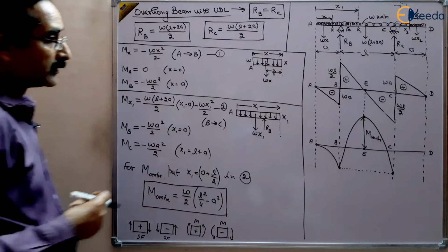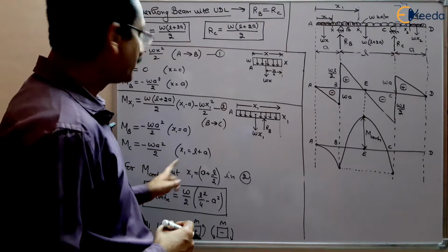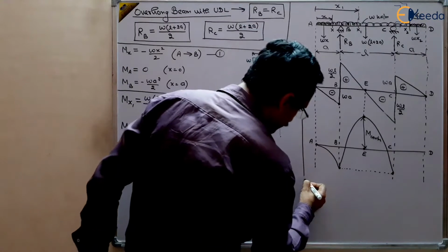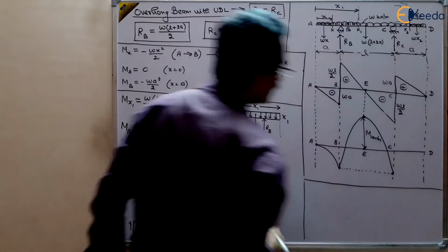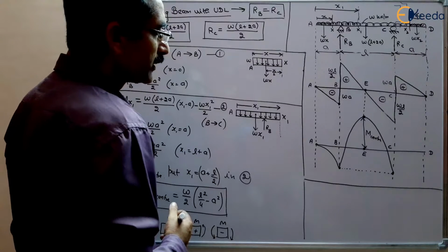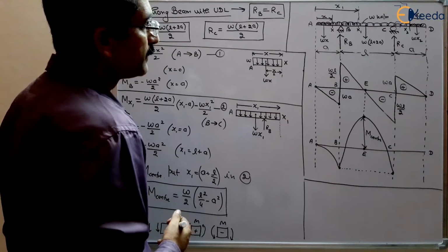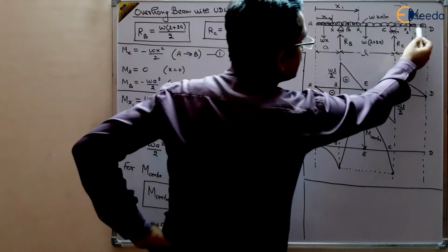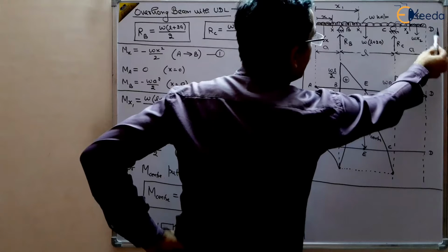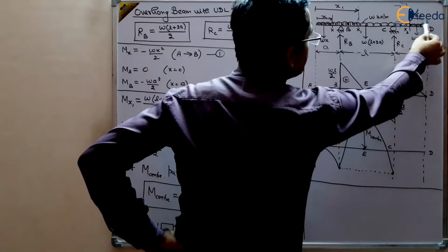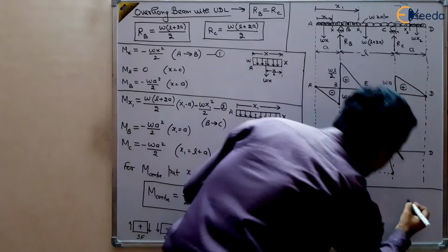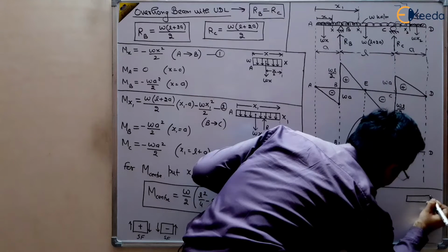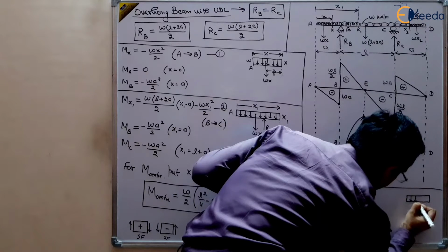Now what is the bending moment diagram between D and C? So I am doing here between D and C. What will be happening between D and C? Between D and C, you will take this section from the free end, take a cross section x2 at a distance of x2 from the D. So I have taken a small cross section, this type of cross section